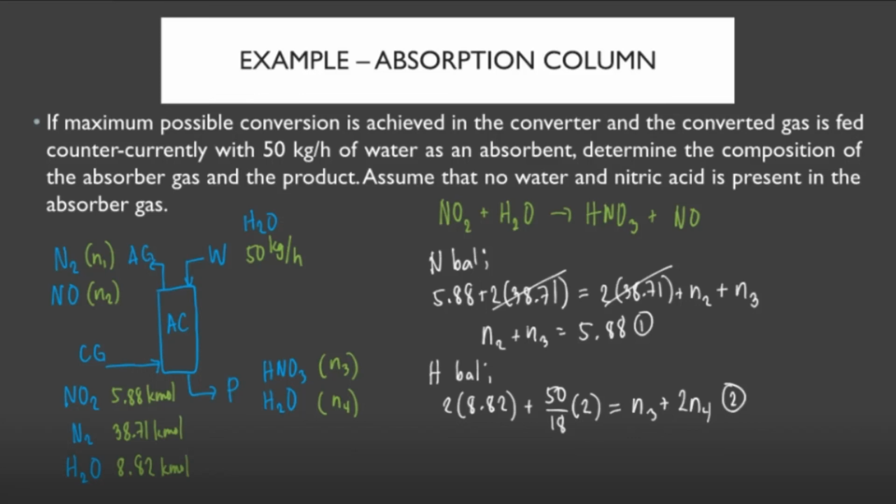Earlier, if you remember, I mentioned that we are assuming 100% conversion from NO2 to nitric acid. Or that's also saying that we are assuming that we have 100% absorption of the nitrogen dioxide gas. That means that we can perform stoichiometry to determine how much nitric acid was formed in the absorption process. For that, let's first balance our chemical equation. So we multiply NO2 by 3 and nitric acid by 2 to make it a balanced equation.